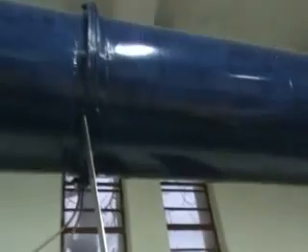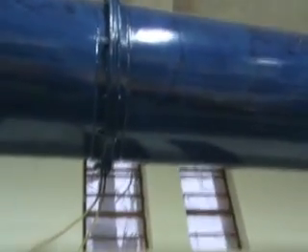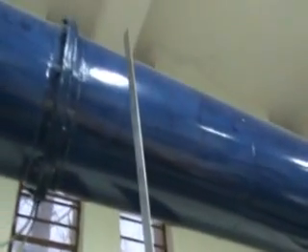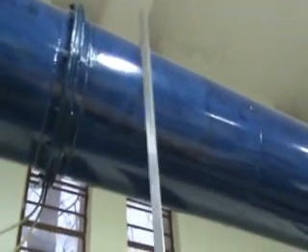Now from this we can find out the pressure drop across the orifice plate, and the dimension of the duct we can take, and obviously if I know the dimension of this duct, the dimension of the orifice plate will be, for this case, half of that. So we get the A2 value over here, and from this we will get the pressure drop.